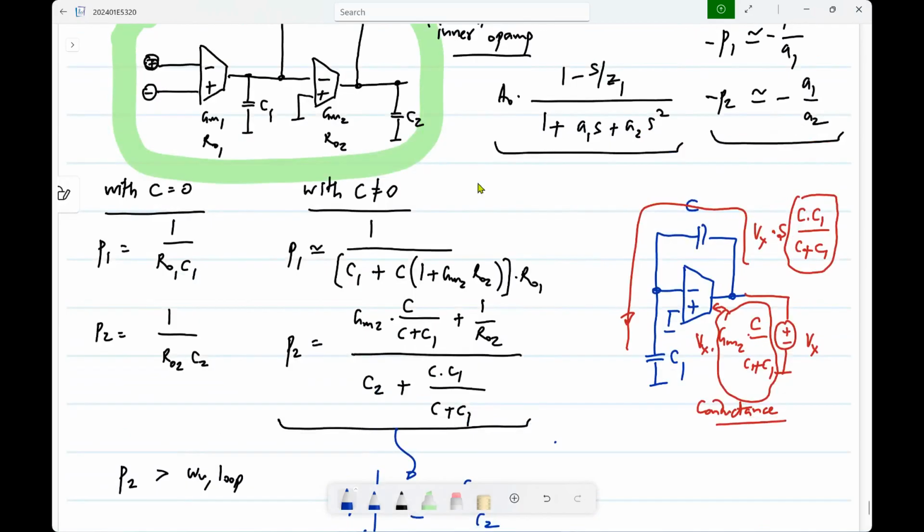Okay. Any questions about this nested op-amps and so on? Any further details, you can do this by simulation. Okay. Because as you can see, there are a number of parasitic elements here. And the more stages you go to, the more poles you will have and so on. So finally, you will have to adjust all these values so that you get good enough stability margins, and that you do by simulation. Okay. Any questions about this type of op-amp? And you can keep on doing.